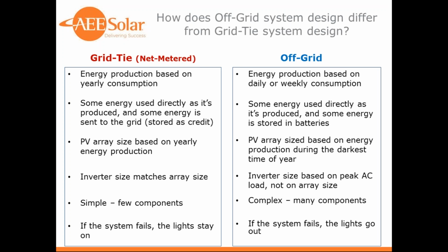In an off-grid system, the PV array size is based on energy production during the darkest time of the year. In North America, that's generally in winter, and of course in South America, that's going to be what we call the summer, but it's their winter months.